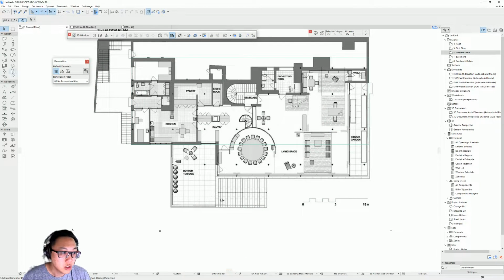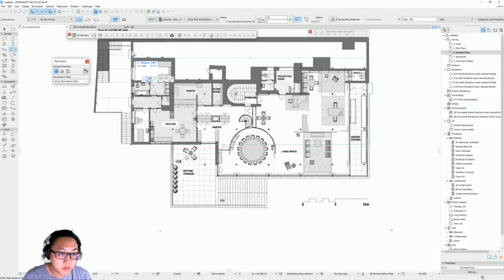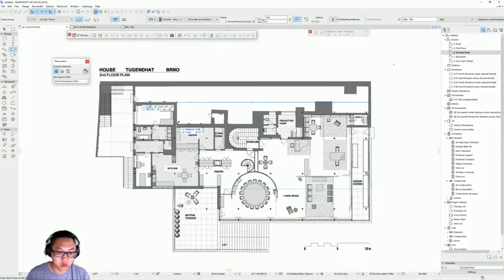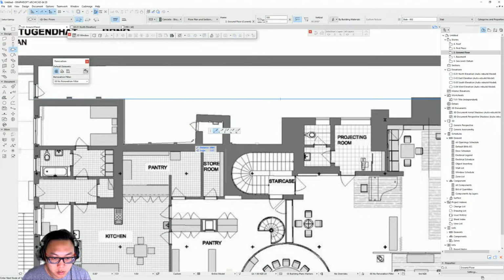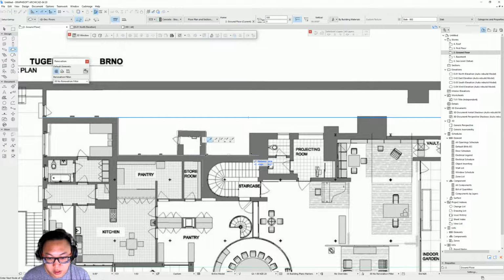But if you were to, let's say, use the slab tool with the polygonal method, this one allows you to just press on each corner, and you can see some guidelines popping up just to help you make it straight. I'm just going to go all around. I don't know what this is, but I'm just going to do it anyway. This is not straight, but I'll make it straight for the sake of the tutorial. This could take a while to go all around, but you have to make sure that everything is straight, so that when you make your walls, everything's going to line up.